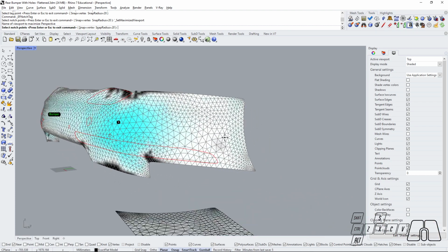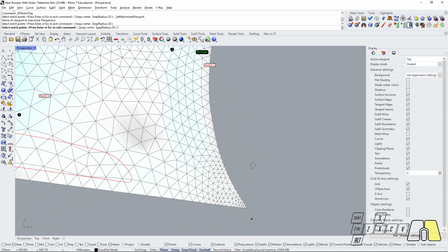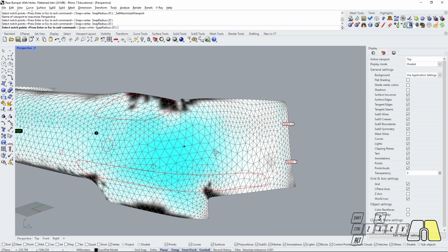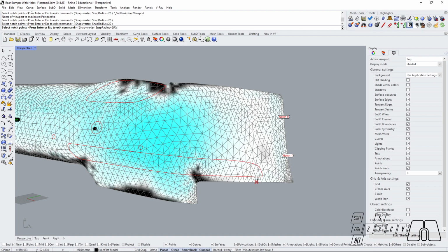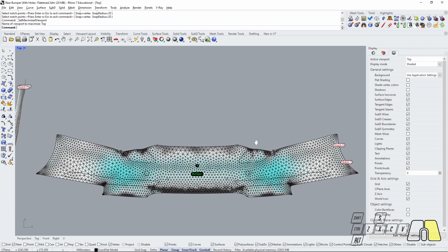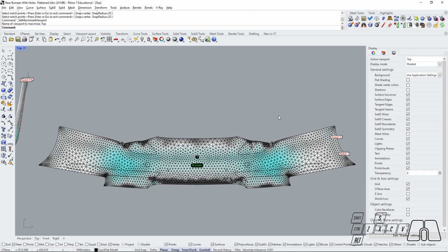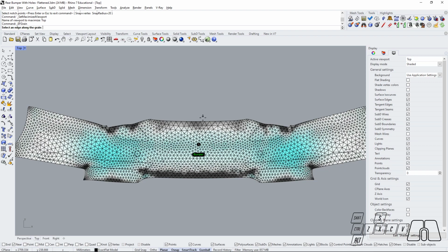So we could add tiny marks at critical spots that we may need to, for example, we could say that here there is a connection with another part, so we could mark it over here if we need to, or maybe there is a specific feature or a sharp edge that we want to mark. So this tool will let us mark any features at the boundaries. So this is going to be there in our flat pattern as well, for example. Then we can go to the grain line tool. The grain line tool is going to let us add basically an orientation for the material fiber.